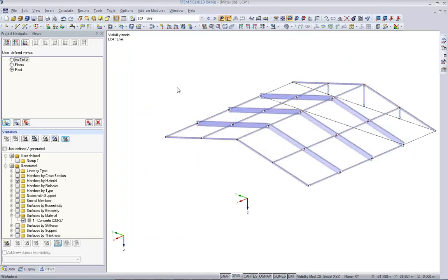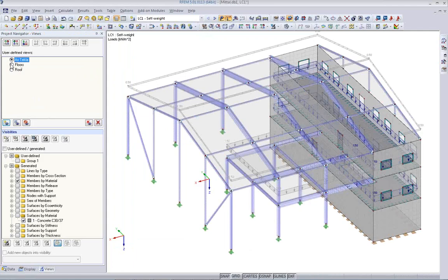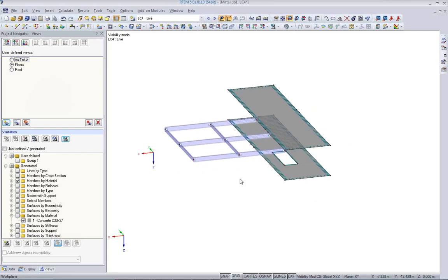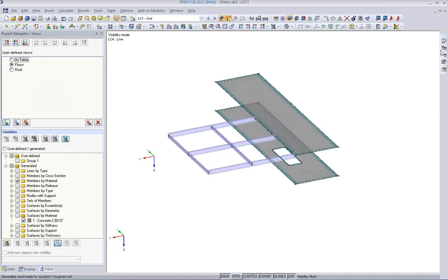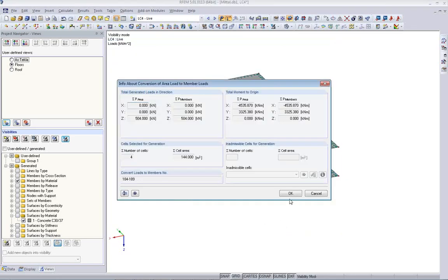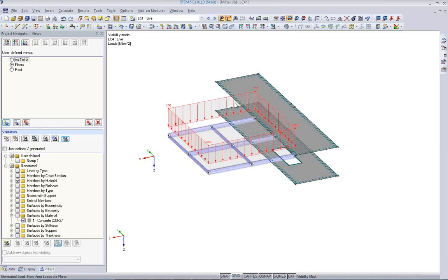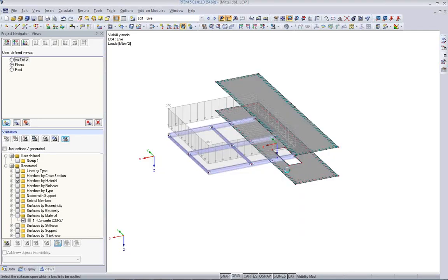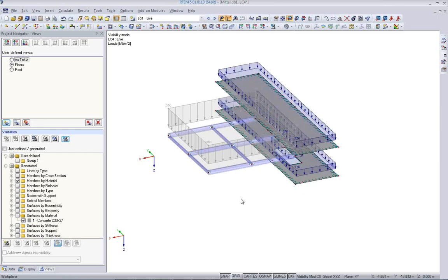Okay, last but not least, we have a live load on the floors, which is basically simple. We can create another surface area. It remembers the last input, so I only need to add the actual live load. Okay, and it's updated here in load case 4, and the same live load, 3.5 as global z direction on the slabs.